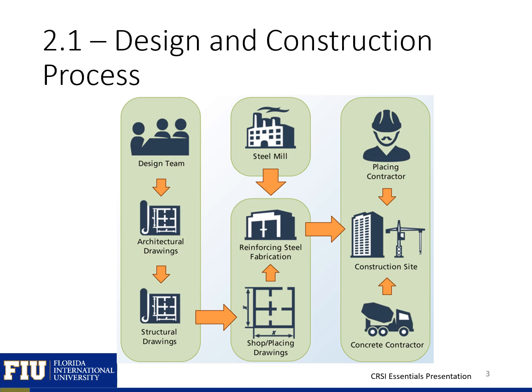As a design engineer, you will specify the number of bars, spacing of bars, size of bars, strength of bars, type of steel, and location of bars. The contractor will then take your drawings and create shop drawings with specific details on the reinforcement, bar lengths, bar diameters, type of steel, and how the actual rebar cage will be constructed. These shop drawings will then be used to create rebar schedules, which show the specific details on the reinforcement and the number of each piece that is needed.